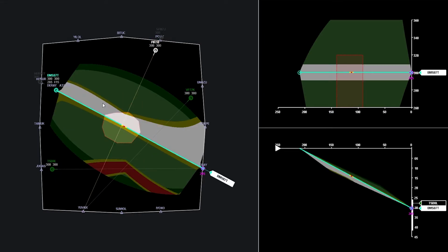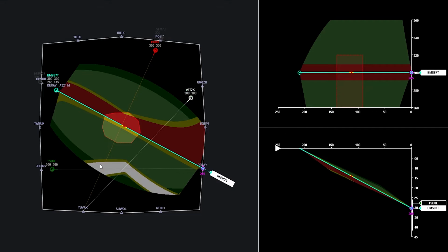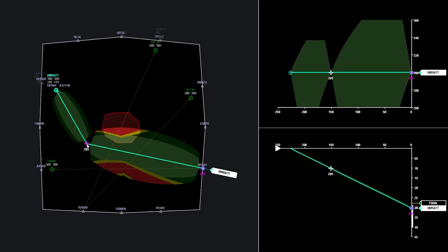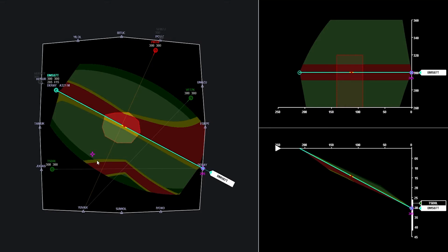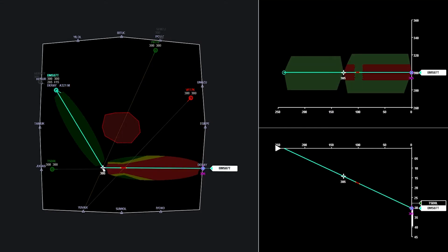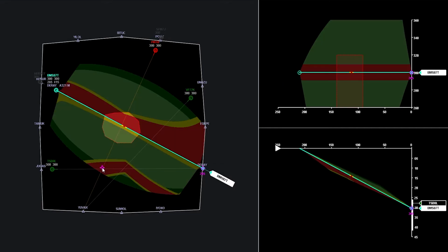the user's perspective. To illustrate, we place an intermediate waypoint on both a green and therefore conflict-free area versus a waypoint that causes an expected conflict at some point in the future. It should be noted that because the intent of all other aircraft are taken into account, the user can be sure not to introduce any new conflict when placing an intermediate waypoint somewhere inside this green area. Furthermore, the required velocity increase to meet the timing constraint at sector exit is automatically taken into account.